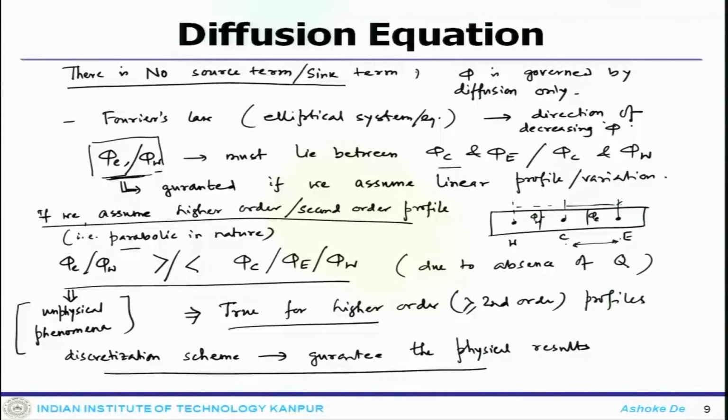That is why in calculations we must do a grid independent study and carry out some grid refinement, and particularly for certain problems of interest, the refinement near the boundary, near particular places, becomes quite important.